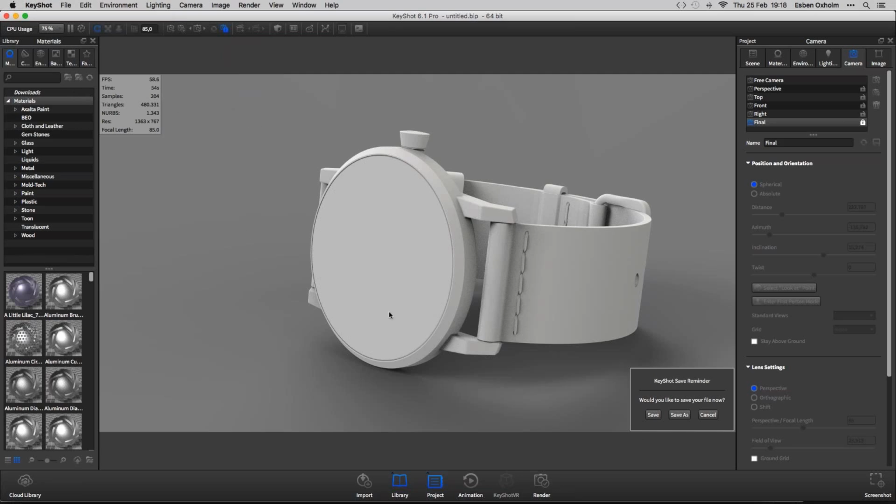Sure. Okay. And then can you touch quickly on why you would model the fillets in the model rather than apply the rounded edges in KeyShot? In my experience, it creates a better result when I'm doing it in the CAD software, and that also makes me able to create different sizes of fillets on one object compared to doing it in KeyShot where it's the same size applied to the entire object. Mm-hmm. So I guess that's why.